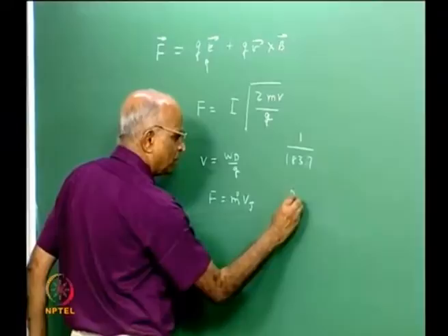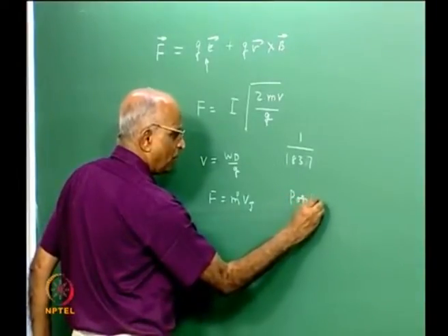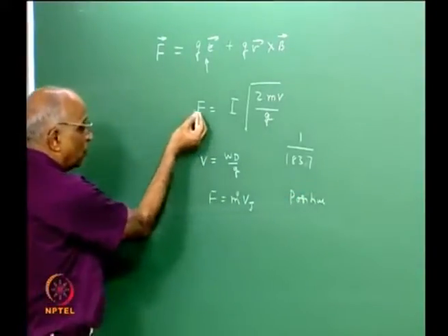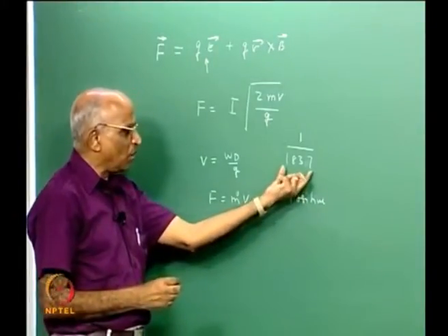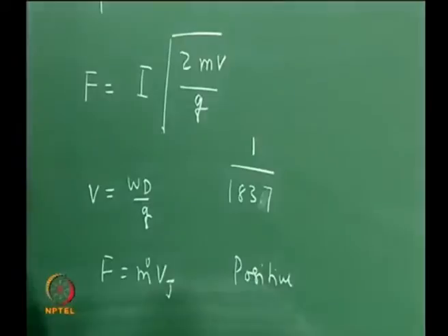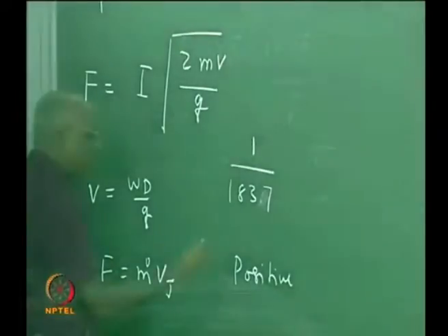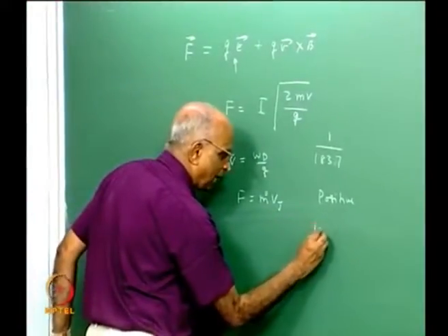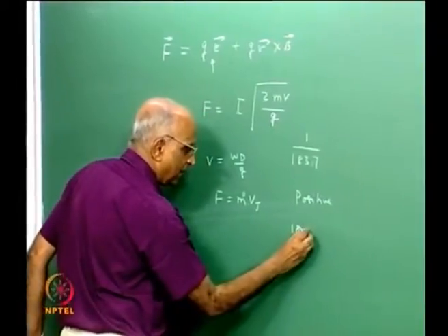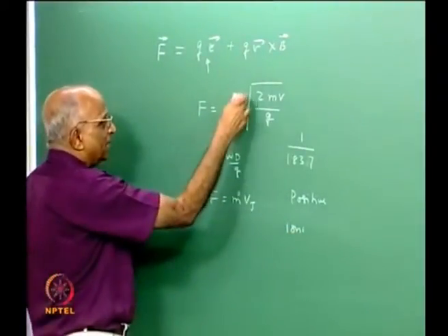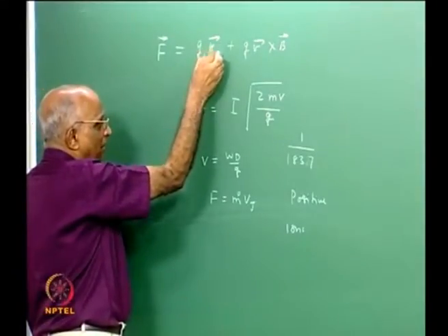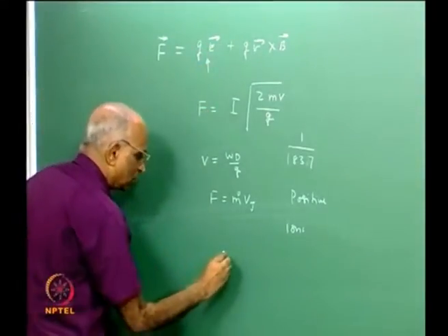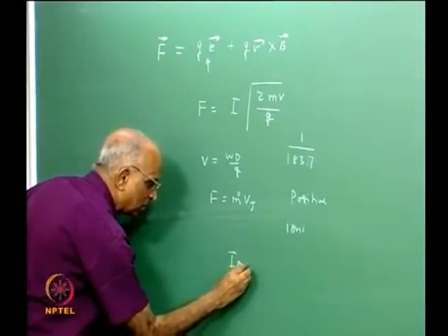Normally positive charges are used for generating forces, and we cannot use electrons because their mass is so small that I do not get any impulse at all. These positive charges are what are called ions, and therefore such a mechanism of using electrostatics, namely an electrical field, for generating a force is also known as ion propulsion.